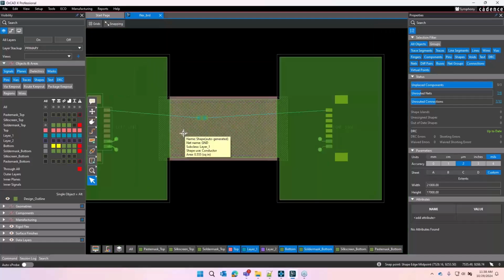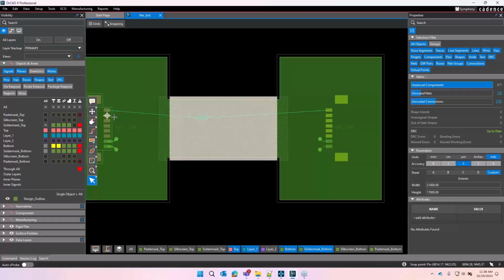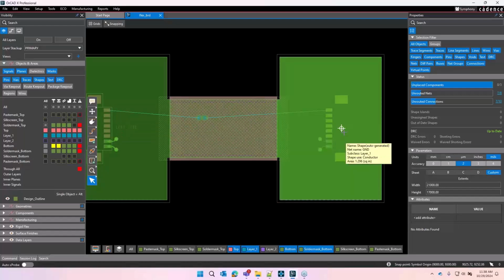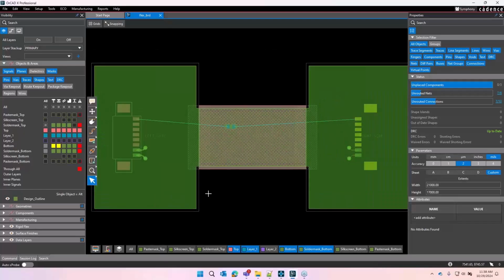And now what I want to do is I'm just going to route a net. I'm just going to take a single net from a component over here on the left over to my component here on the right. I want to kind of route it through this area. This starts on the top, this ends on the bottom, and this flex layer, as you remember from the stack up, is traveling on internal layers 1 and 2.